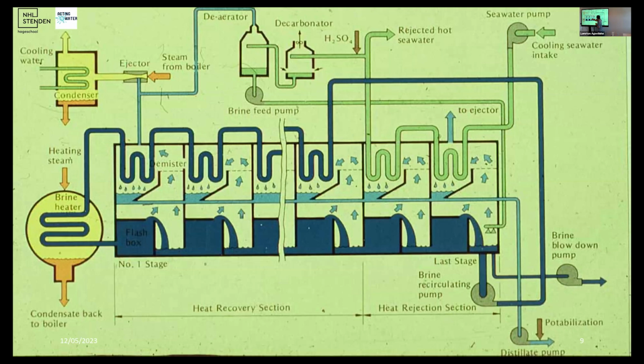Well, good question. Normally in desalination processes, especially thermal processes, and by the way also reverse osmosis, you reach a very high purity level. Because when you distill and condense, you basically just get clean, distilled water. And distilled water cannot be distributed. It has to have a minimum conductivity, a minimum amount of salt in it. So the potabilization here means that after you collect all the distilled water in the condensation chambers, you have to pass through a post-treatment process, normally a remineralization step where you re-add the salts. It is a little bit controversial, to say the least, that you remove salts and then re-add them at the end. But that's how thermal desalination systems work.